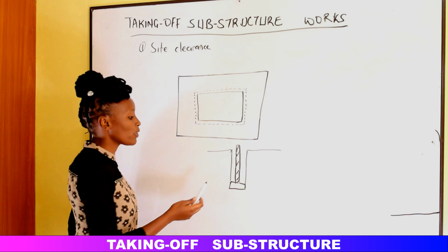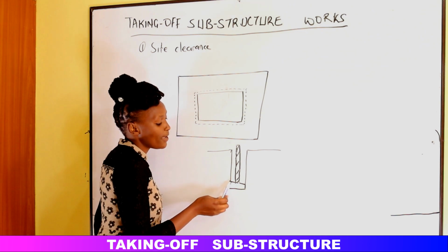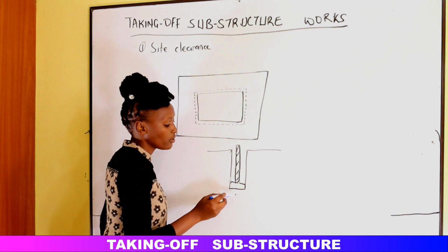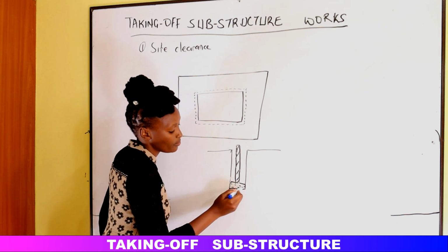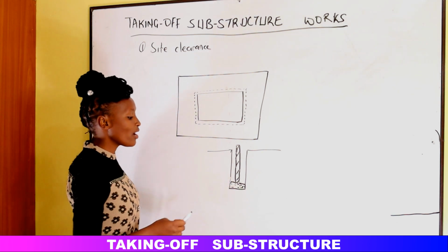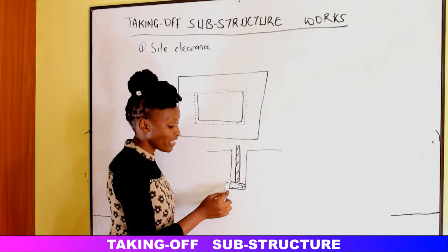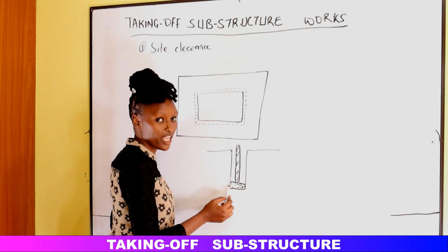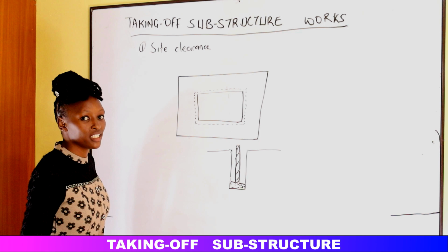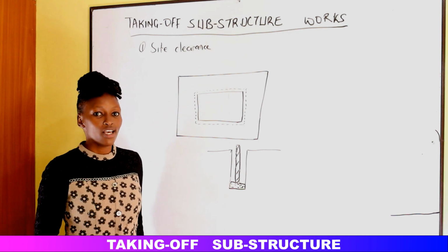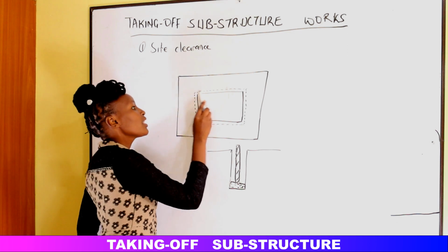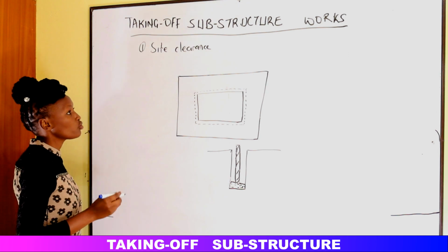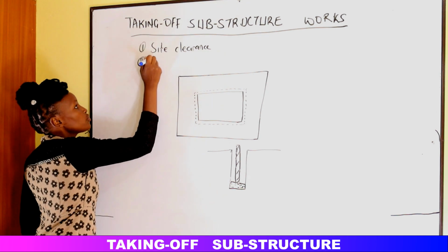And we have said this foundation spread is the distance between the edge of the trench and the wall, where the concrete below, in the strip foundation, will be. Because we will have to dig a trench, lay the concrete inside the trench, then construct the wall at the center of the strip concrete, the foundation concrete, in other words. So site clearance is usually measured for that area.